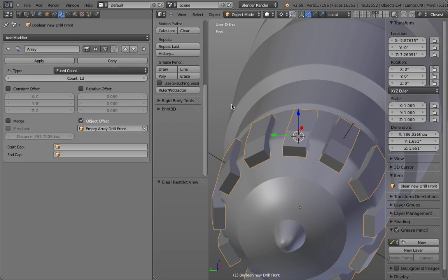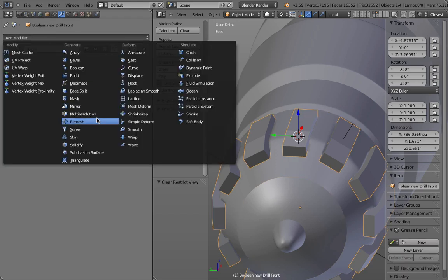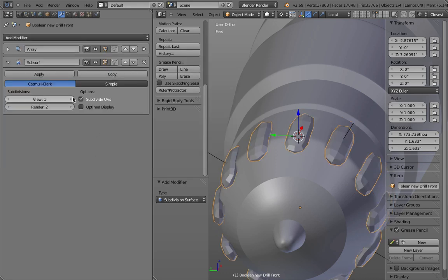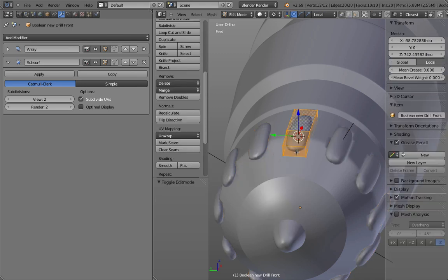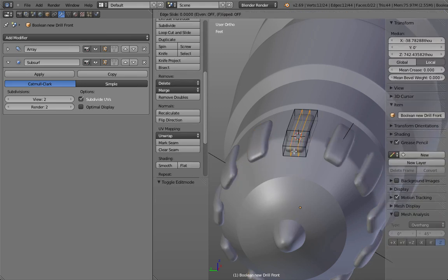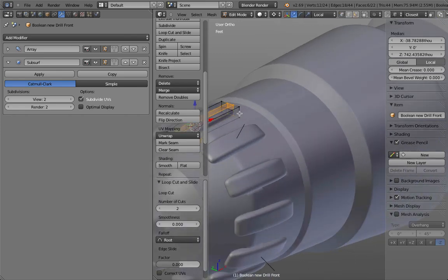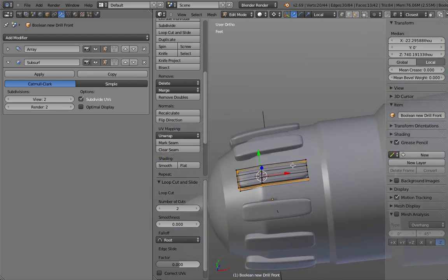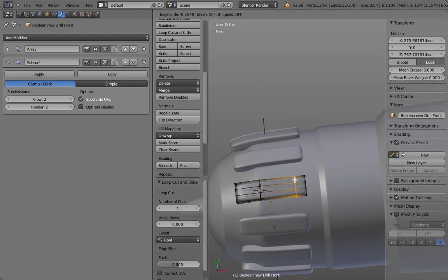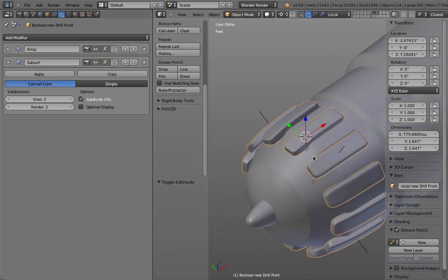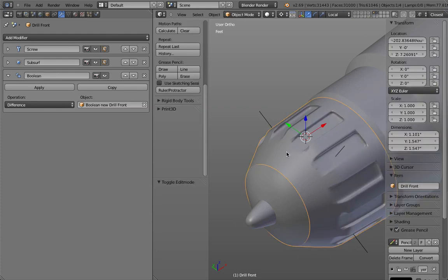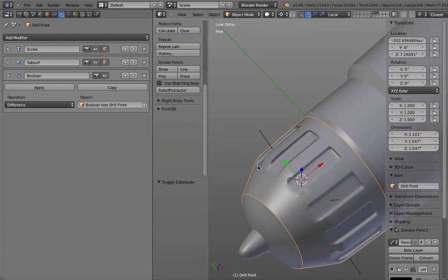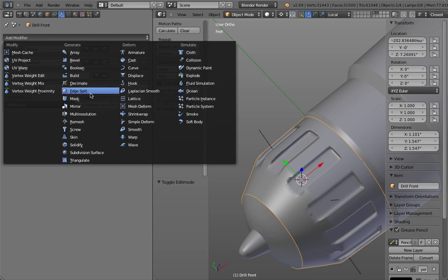And then if I want at that point to have nicer rounded edges, I could add a subsurface modifier, not too much, just 2 or something, shade smooth, maybe make 2 loop cuts, enter, maybe 2 loop cuts, enter, maybe here I add a loop cut to the end to sharpen that rounding, hide, edit. Okay, great. And then edge split.